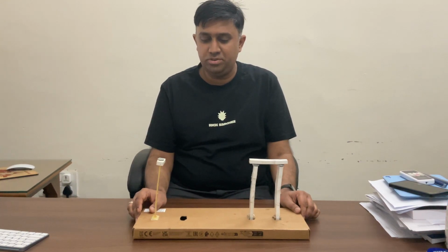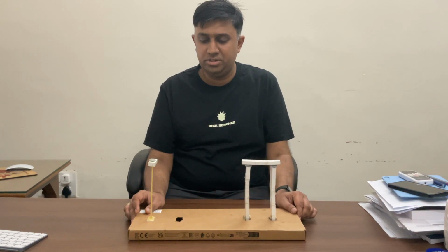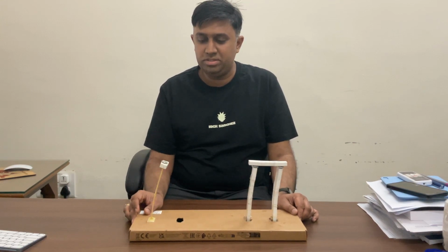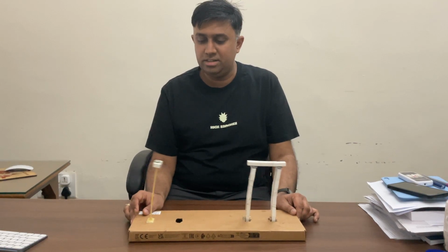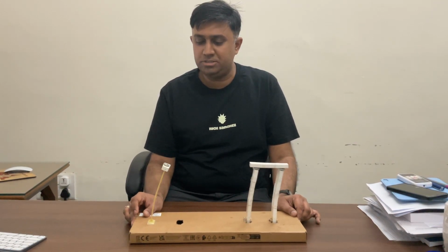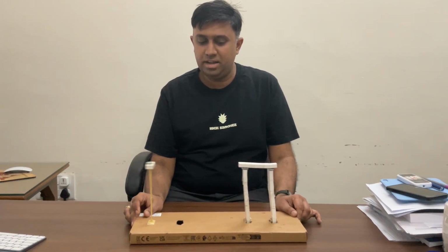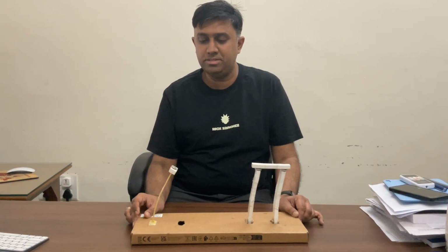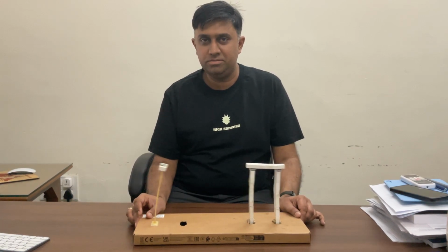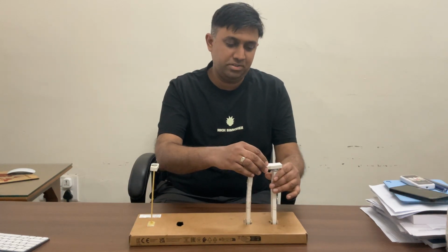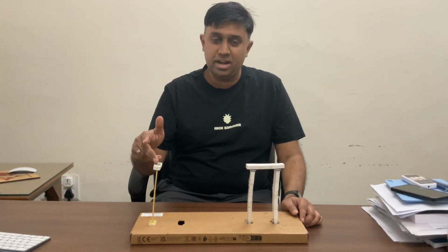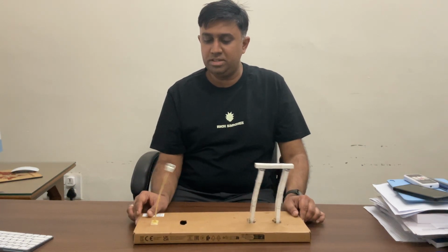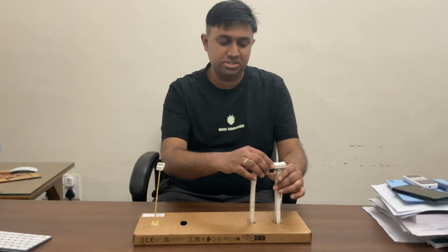I am starting with low frequencies, and now I am gradually increasing the frequency, and now I am reaching a frequency at which the structure to your left has started resonating, right? I hope it is evident if you compare the response of the structure to your left and to your right that the structure on the left has a very high amplitude in comparison to the structure on the right, okay? This is precisely what happens when there is a difference in the damping ratio, because the structure to your left had a significantly smaller damping ratio than the structure to your right, so its amplitude during resonance was much higher than the amplitude of the structure to your right.